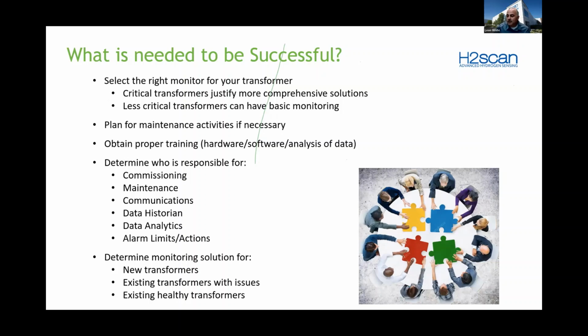And of course, once you identify what are your critical transformers and what are your not so critical transformers, and then different levels of monitoring, you want to determine what are your solutions for your new transformers and your existing transformers with issues. So of course, a transformer with issues, you're probably going to want to put more monitoring on than a transformer with no issues.